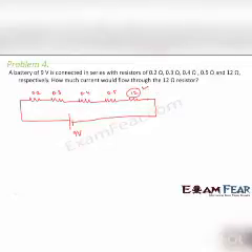Right? Now if you look at it, this is the positive terminal of the battery, this is the negative terminal. So the direction of conventional current would be from positive to negative. So that means this is how current will flow. Now since these resistors are connected in series, the same amount of current will flow through each of the resistors. So the amount of current which will flow through this 12 ohm resistor is also I. So what will be the value of I?